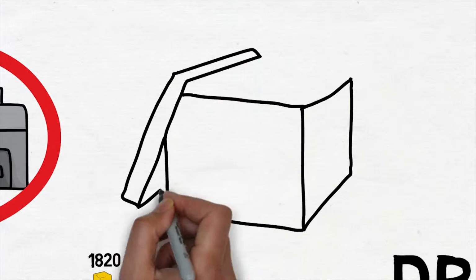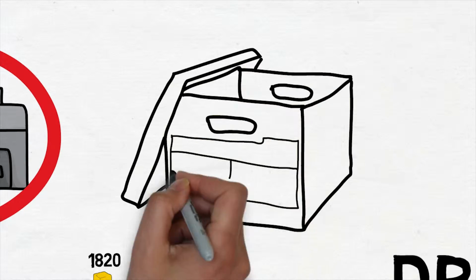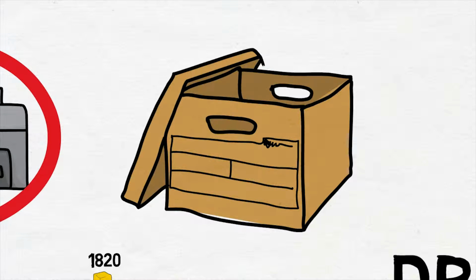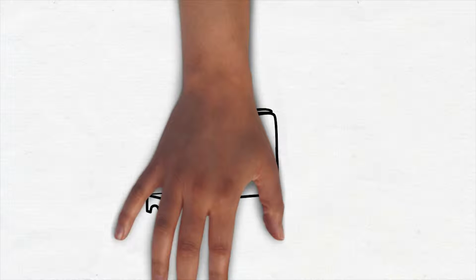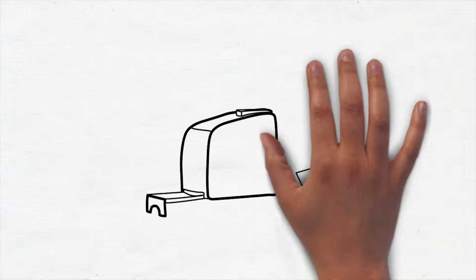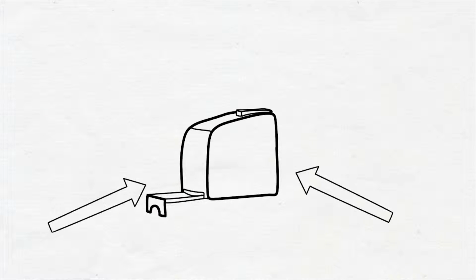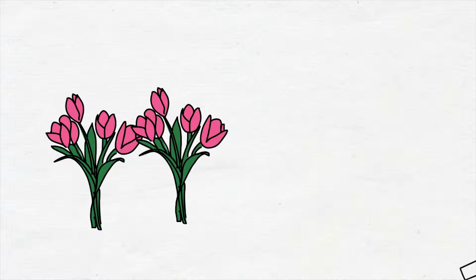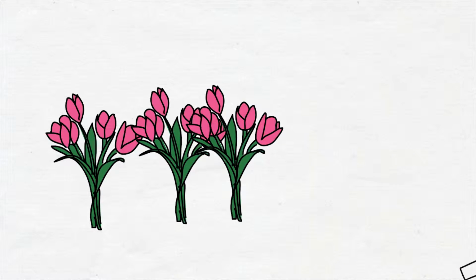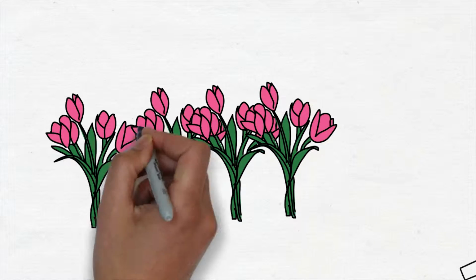There is no reason for accepting that Monge specifically called his newly defined method of projection either first angle or third angle projection. He demonstrated his theory simply by depositing an object in a box of which three sides had been removed. Subsequently, he showed how the object could be viewed orthographically from three different directions and then be projected on the sides of the box behind the object to show the three views in perfect light with one another when the sides are hinged back to form one plane. From this description, it becomes clear that Monge was engaged in demonstration of first-angle orthographical projection as it is known today. With the exception of Holland, the whole industrial world of 1850 employed first-angle orthographic projection.